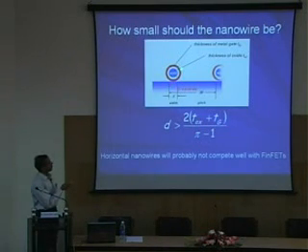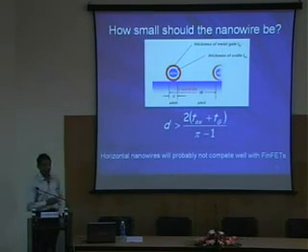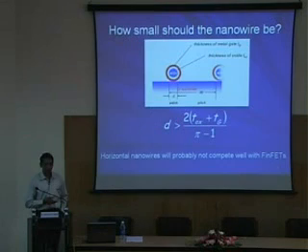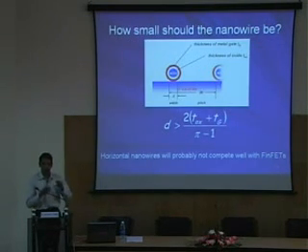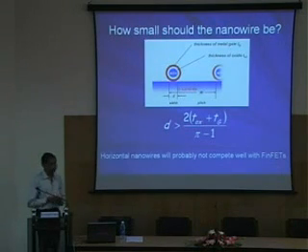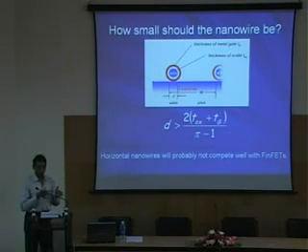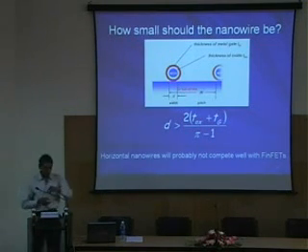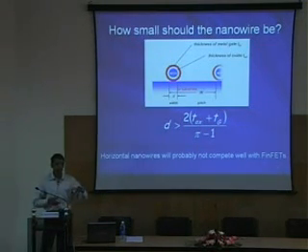If I use my conventional technology, if my oxide thickness is about 5 nanometers, if I am using high-K dielectric, and if my poly thickness is about 5 nanometers, that means the diameter of the wire has to be greater than 10 nanometers. Whereas we are planning to use nanowires in order to have better characteristics for our devices, and the nanowire diameter is of the order of 3 nanometers, 4 nanometers, 2 nanometers. On the other hand, if I had to build an integrated circuit using these nanowires, d has to be greater than 10 nanometers.